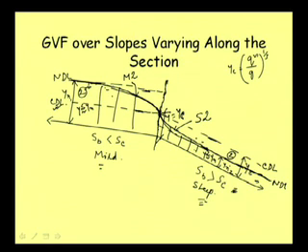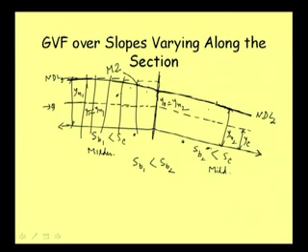Okay. Another point I want to highlight is that in this case, when we are computing the M2 profile, we are moving on to the critical depth point. We start from here because we know that here the depth will be the critical depth. But in our earlier discussion we said that the M2 profile at upstream meets the uniform depth line asymptotically, and at downstream meets the critical depth line normally.